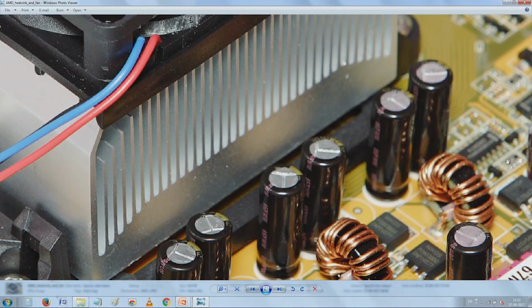And then LEDs are being improved such that a LED typically which gives about 250-300 milliwatts does not need a separate heat sink. If you can just put it directly on the copper lead itself, it can be made to carry a certain amount of heat. So, somebody is working on these things all along.